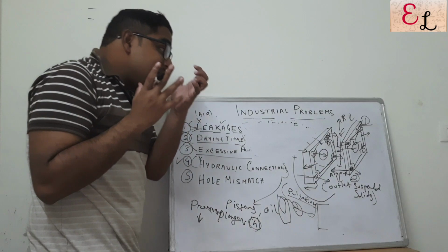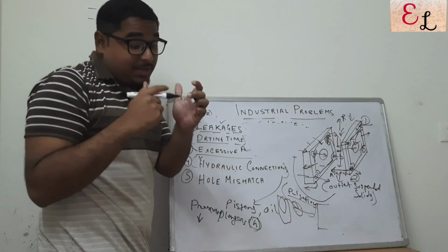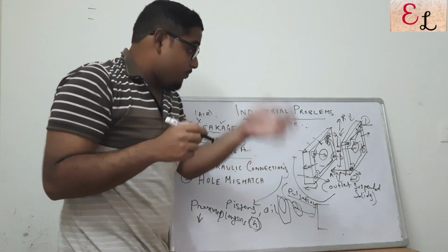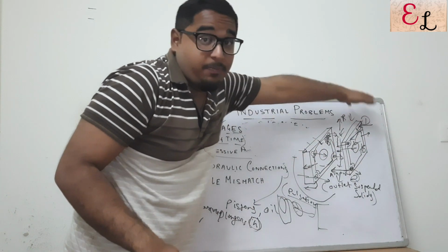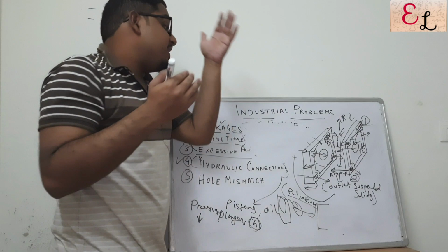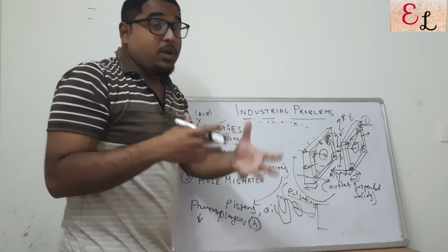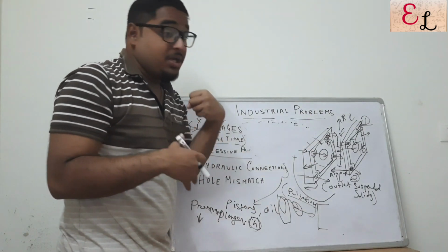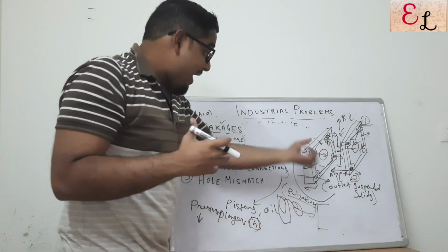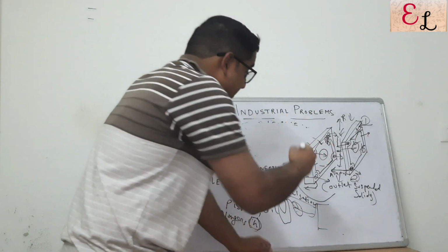So we understand the problem, my friends. Very important, this side of the filter press, the other side, is not at all having any incoming liquid or any cake deposition or any pressure as such. All the pressure is concentrated at the outlet and all the outlet is taking place from here.